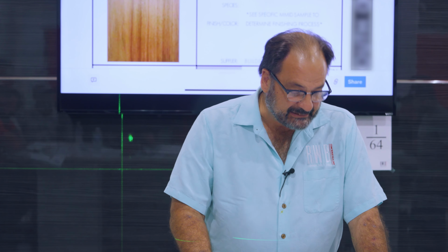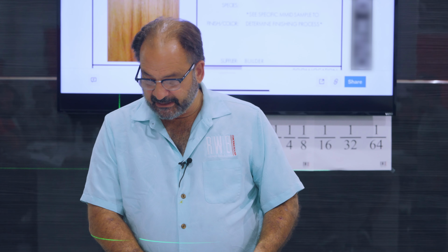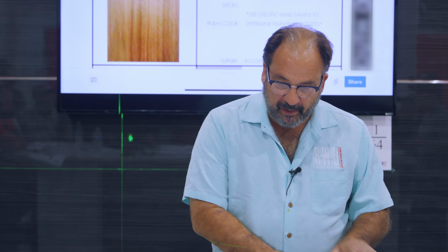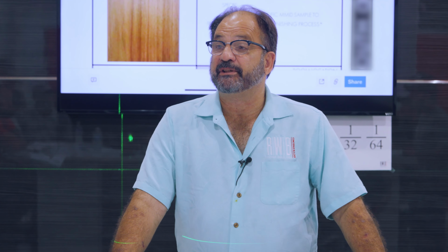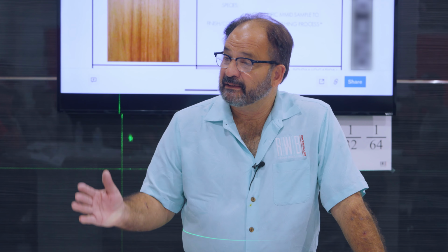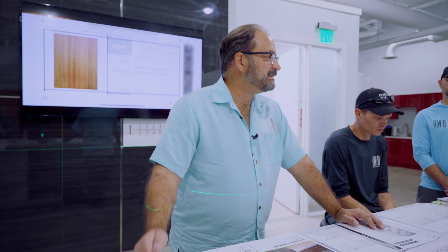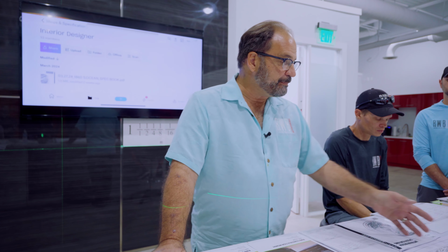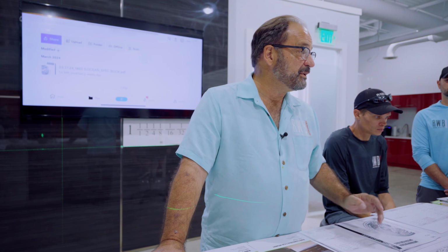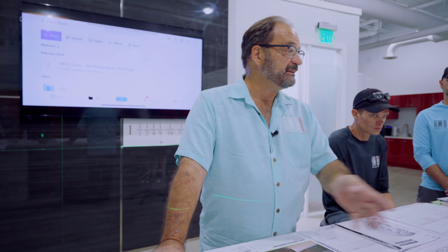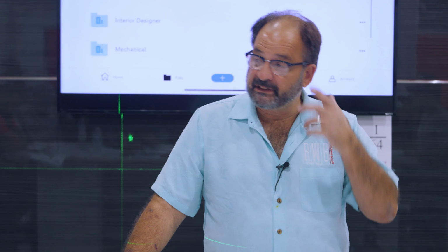This will tell you venting. This will tell you everything you need. It's important that you have all this information before you start. Last week, Dan was asking about layout. You have them lay out the entire job on the floor. When you lay out the job on the floor and you go back, you will see if the window's off. You will see if the center line's not right. You will see if there's not enough room for a piece of plumbing. Whenever I do this, I always say, let's lay the entire job out.